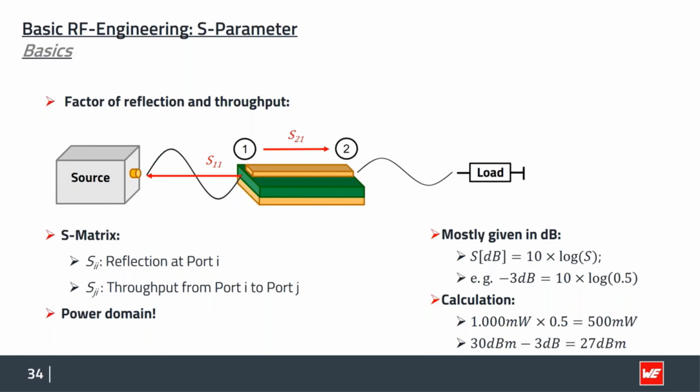To look at the losses through reflection, we do a measurement on the S11. So we send the signal to our device under test and we look at what's coming back, what is reflected. And of course, this is then what is caused by our mismatches of the impedance.